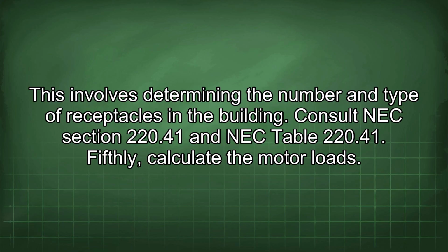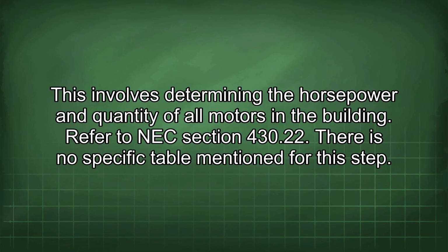Fifthly, calculate the motor loads. This involves determining the horsepower and quantity of all motors in the building. Refer to NEC Section 430.22. There is no specific table mentioned for this step.